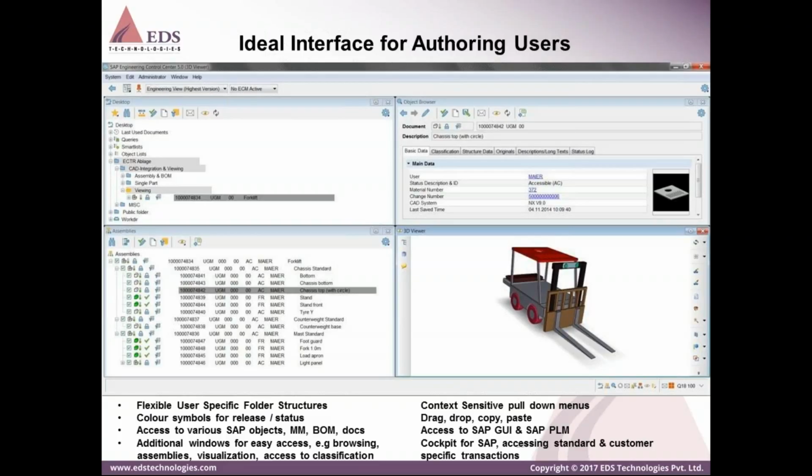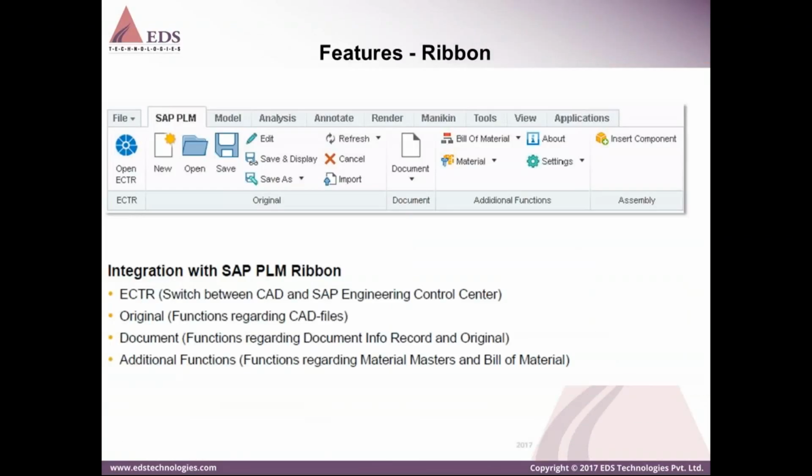Then you also have engineering change management. Any design that goes through a revision needs to go for a change. You go for engineering change management right from ECR to ECOs and the engineering change number that gets generated. All these things can be managed within this tool, Engineering Control Center, and also the material masters and BOM masters with visualization as part of the package.